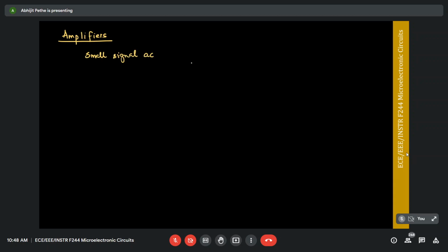So in other words, we'll have, say, a 1 millivolt or a 10 millivolt signal, and we want to amplify that signal. So many times, at any point in the circuit, you will have a DC voltage and a small signal AC voltage. We are interested in understanding how this small signal moves through the circuit. Eventually we want to design an amplifier. We want to track this small signal as we look at the various nodes in the circuit, and hence see if we can amplify the signal.